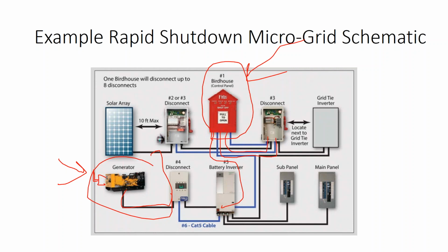What is in code is to say that your backup systems and your emergency backup systems, the system level disconnect for your backup system has to be located in a different spot than your main service disconnect. And so like on a generator, the fire department shows up and they pull power to the building, but they see the generator. And there's no confusion on, if I pull the power to the building at the meter, does that kill the whole building? They see that there's a disconnect in a separate location for the backup system.